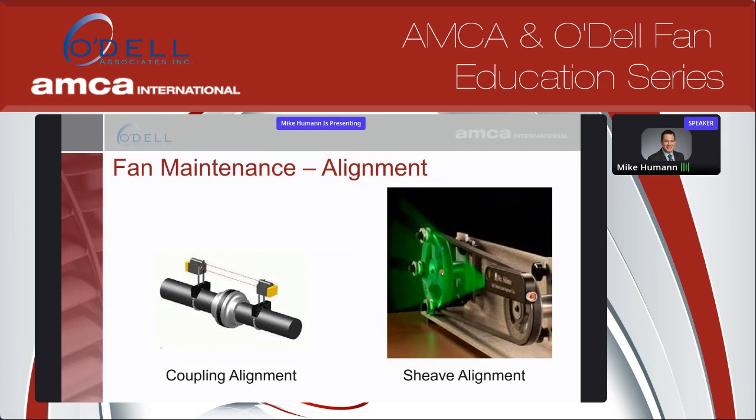And then on the right-hand side, you see sheave alignment. You see another laser type tool used for sheave alignment. This is nice because you can use this by yourself. You don't need an extra set of hands, but not everybody has a laser alignment tool. And this is good to make sure that you get the best longevity out of your belts.